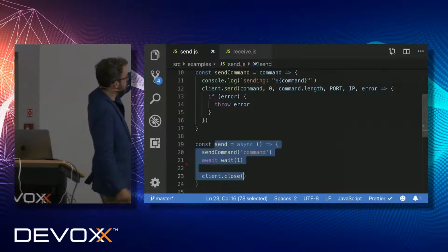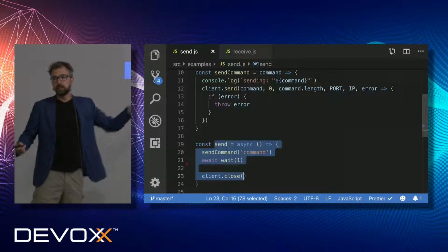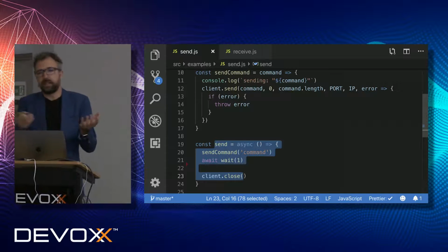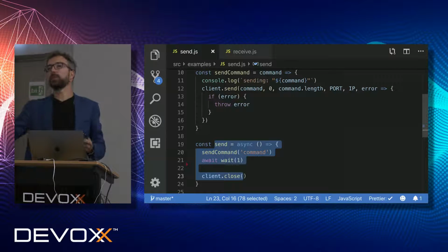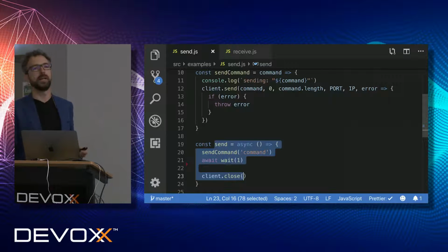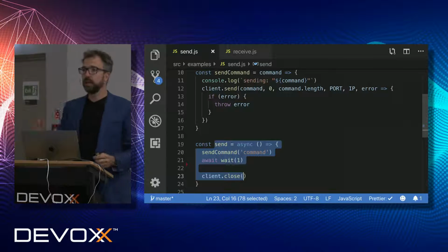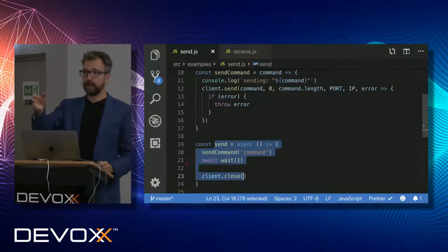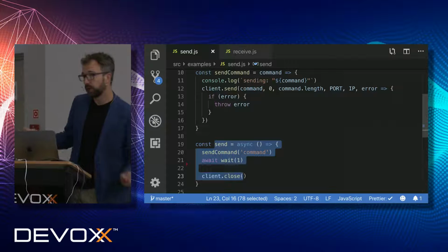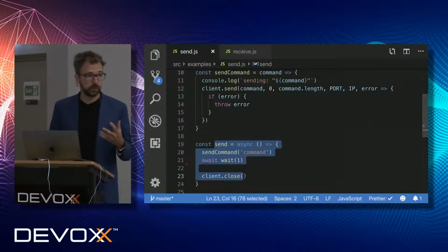As you will see, the first command is "command", which is very specific for this drone. It basically puts the drone in the SDK mode. With the command, you're basically telling the drone, I'm going to send you more commands, so please be receptive for it. And at that point, it also starts sending back the telemetry to your laptop or to your code, so you can start interpreting what the drone is doing.